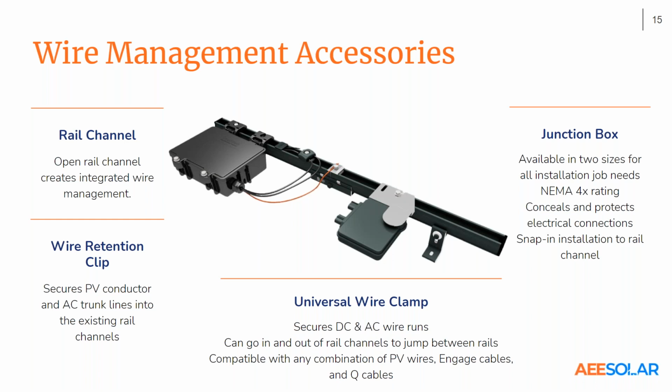The thing is though, a lot of times the splices actually just go on like a hot dog bun, so you can do that up on the roof. If it's a simple array, you'll actually see best practice where they'll attach everything on the ground so they don't have to attach as much on the roof. So they'll just be putting down their L feet and then they can just snap in the rail with everything pre-attached once it's on the roof. If you have something a little bit more complex, it's probably best to put the rail on the roof. If you have to have any splices, put on the next piece, cut off the end with a Sawzall, and then add everything up there. But most arrays are pretty simple, and you can do a lot of this work on the ground.